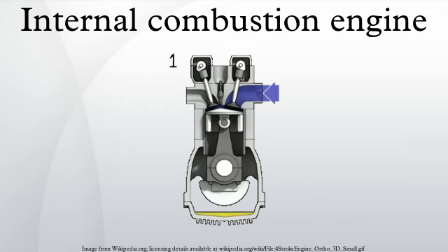Higher thermal stability allows for greater temperature difference between the lower and upper operating temperatures, hence greater thermodynamic efficiency. The thermodynamic limits assume that the engine is operating under ideal conditions: a frictionless world, ideal gases, perfect insulators, and operation for infinite time. Real-world applications introduce complexities that reduce efficiency.